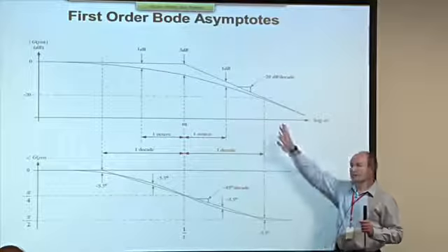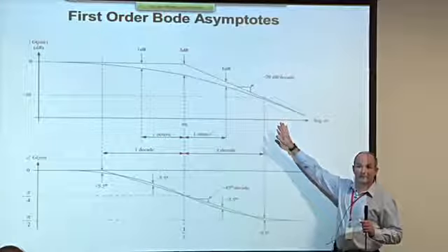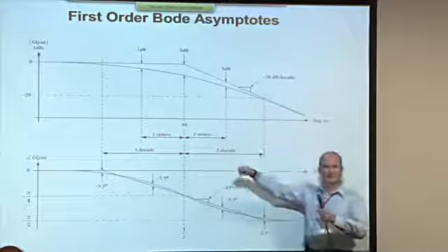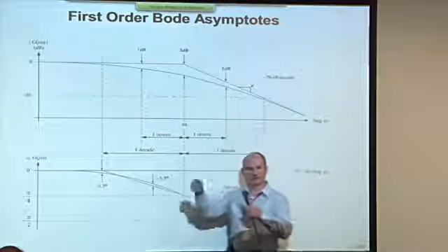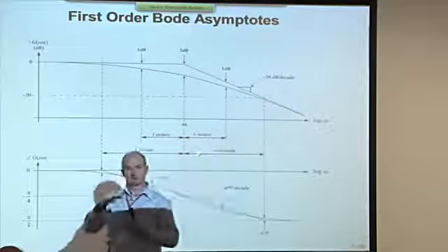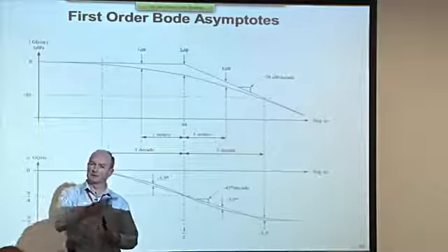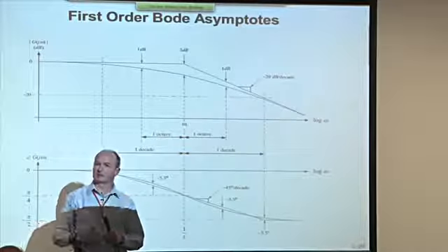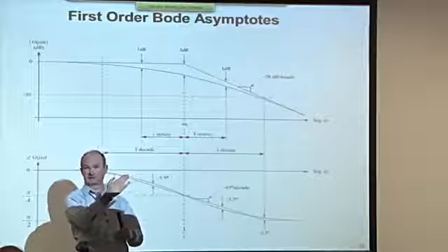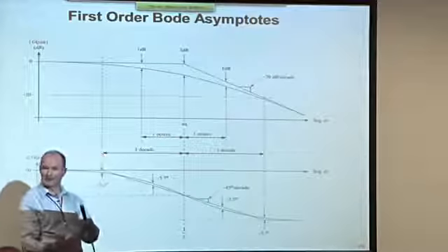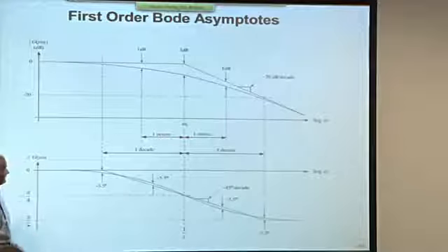But actually, when you look back at the graph paper, when people used to plot these things by hand, you had log linear graph paper and you would go in and plot them. The graph paper was always scaled so that the slope was exactly that. A minus 20 dB per decade slope was exactly minus 1. It was 45 degrees going down. So they're still called minus 1.